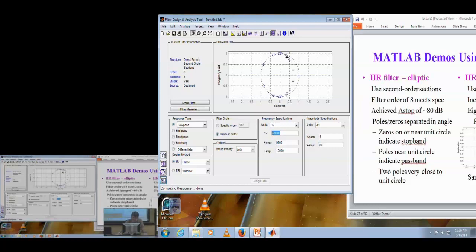All right. So, usually the poles are in the pass band and the zeros are in the stop band. Occasionally you might see a zero in the transition band. That certainly can happen. In fact, it's happening here. So where's the stop band? The stop band frequency in hertz is 12,000. What is that in radians per sample? Pi/2. Right. So the stop band frequency is right here. You'll notice there is a zero in the transition band. And there's also a zero very close to pi/2, but to the left of it.